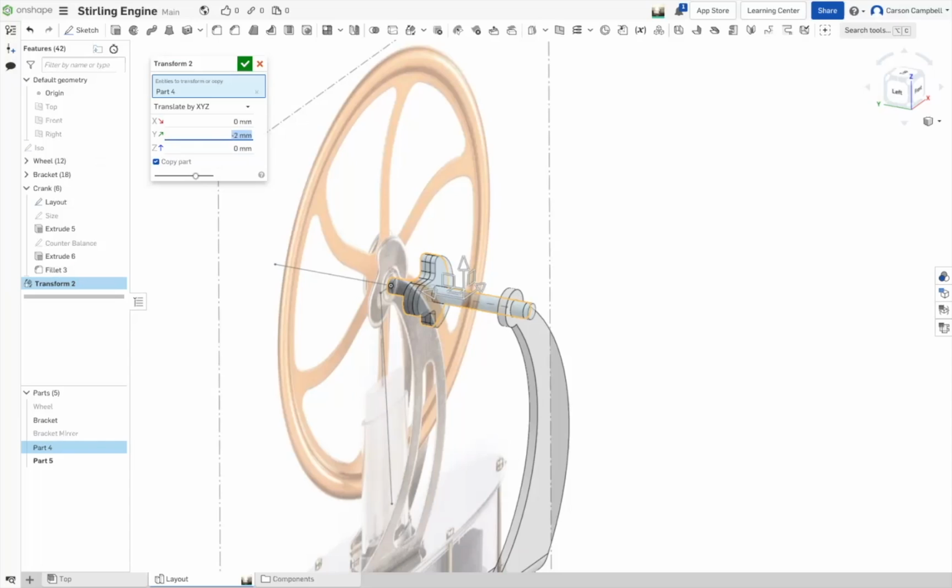Keep going. Now you need to put a knuckle on this. You're going to put a small shaft on this, so you better have more space than that. That's a bit out of size, but I would go 2 and more than that, because that's material thickness. You need to keep going negative. One more, -4, and say okay.